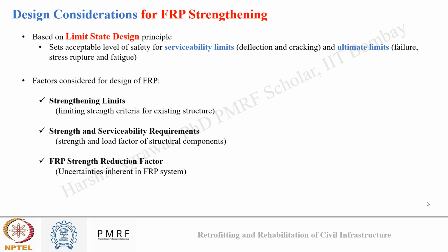Okay, so basically the design is based on the limit state design principle. And what is this limit state design principle? It sets an acceptable level of safety for the serviceability limit. My serviceability limit is the deflection and the cracking, and the ultimate limits are failure, stress rupture, and fatigue.